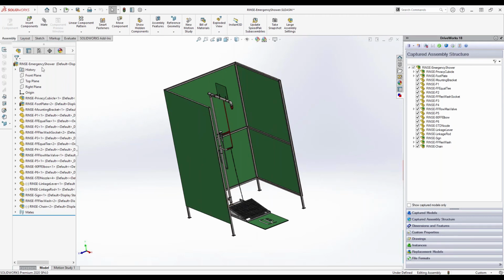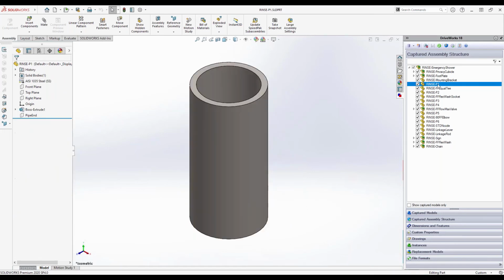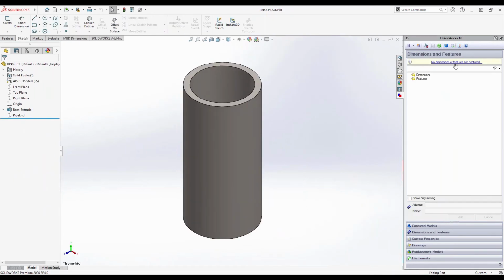Alternatively, we could start with a blank assembly and add in a generative format. So you're going to start with nothing and then add as needed. So literally insert components, create mates, drive them in a very specific way. And that enables a whole other world of opportunity for very particular automation. But anyways, just a single example of how you might link any given part file to DriveWorks.